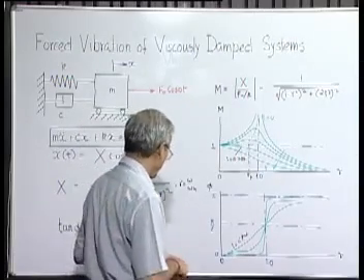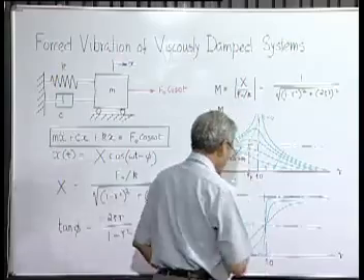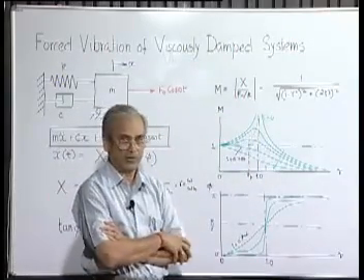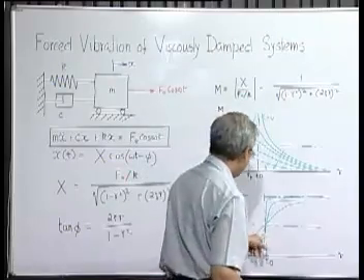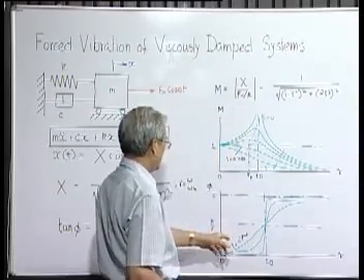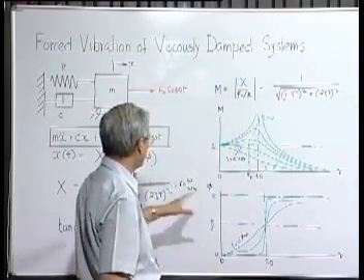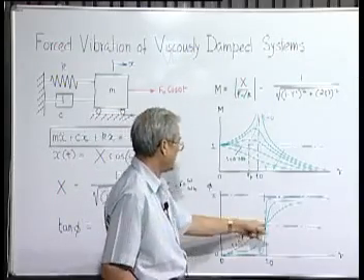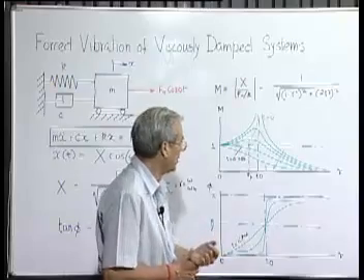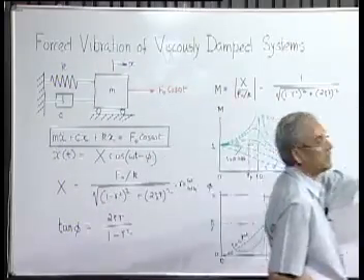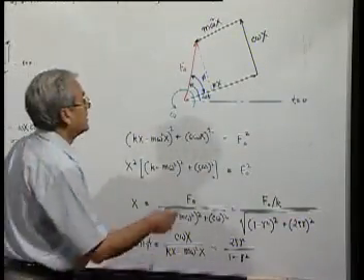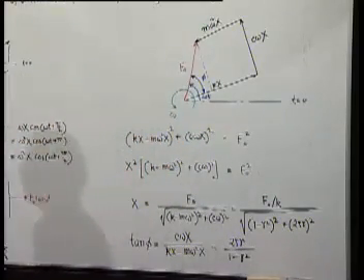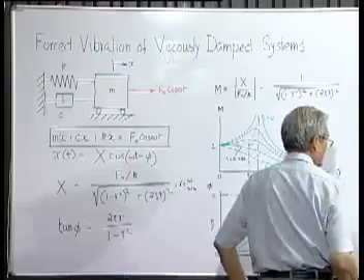So, for example, here we find that at r is equal to 1, the phase difference is always pi by 2. That means, irrespective of the damping, the phase difference between the excitation and the response is always 90 degrees. Now, why is it so? It can be very easily explained with the help of this diagram. Say when r is equal to 1, what does it mean?